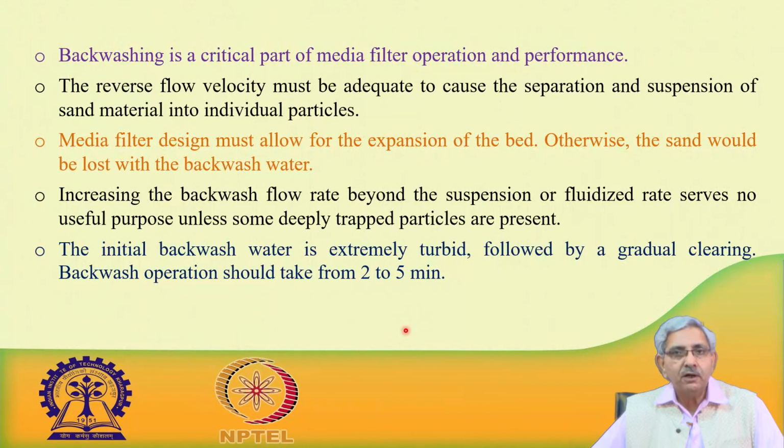Backwashing is a critical part of a media filter, and the reverse flow velocity must be adequate to cause separation and suspension of the sand material into individual particles. Media filter design must allow for expansion of the bed, otherwise sand would be lost with backwashing.